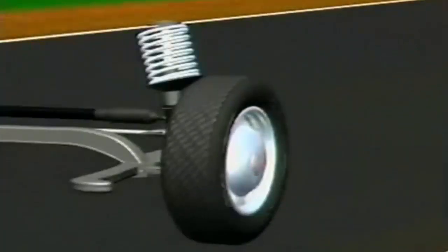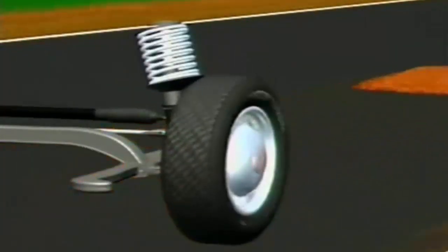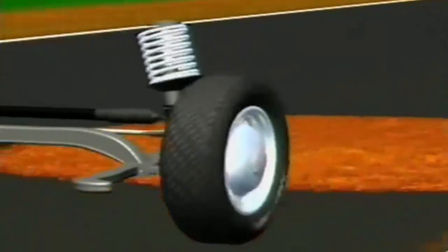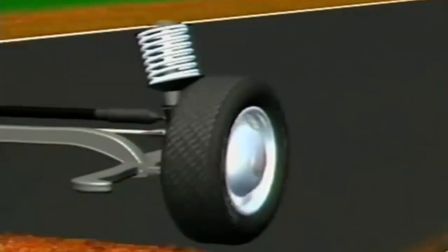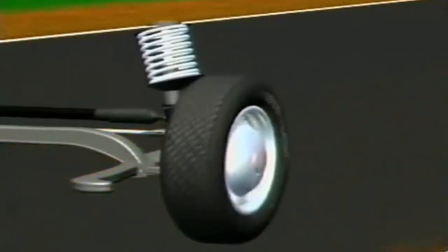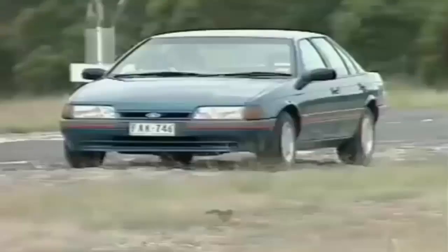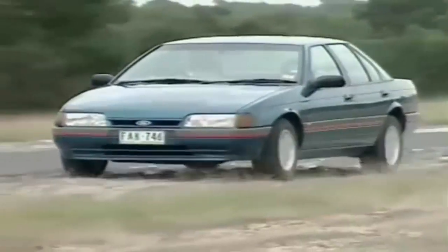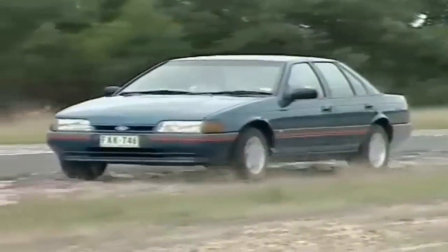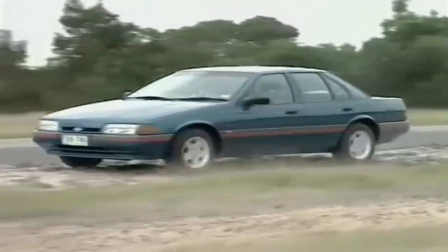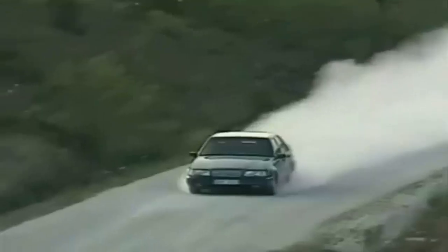Vehicle ride and handling can be improved by keeping unsprung mass as low as possible. When large and heavy wheel assemblies encounter a bump or pothole, they experience a larger reaction force, sometimes large enough to make the tire lose contact with the road surface. Wheel and brake units that are small and light follow road contours without a large effect on the rest of the vehicle. At the same time, a suspension system must be strong enough to withstand loads imposed by vehicle mass during cornering, accelerating, braking, and uneven road surfaces.